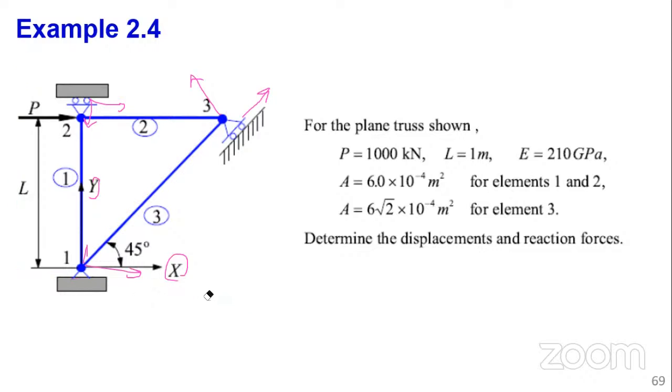So with that, only what we need to do. The other time we were transforming displacement. Let's see, now that it's boundary conditions, what will be transformed. So if you look at this, this is the given information. You are to determine the displacement and the reactions, the displacement at each of these nodes. So you have to look at the boundary conditions so that you determine which ones are unknown. There are those that you can already determine outright. If you look at this pinned support, there's no vertical, no horizontal displacement. So U1, V1 is equal to 0.